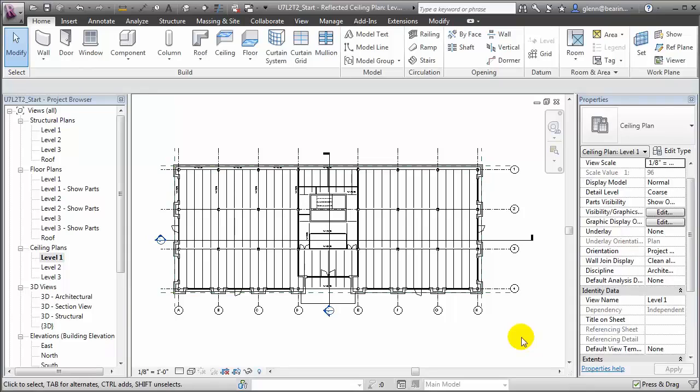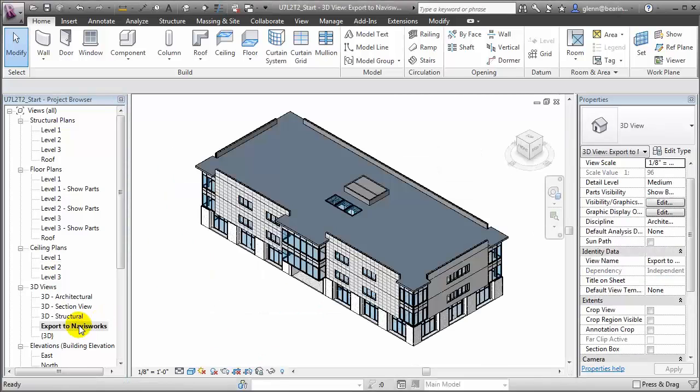Using these same steps, we can select all of the building elements that we'd like to assign to location-specific tasks from the building model on each of the different floor levels and assign them to appropriate task IDs for Zone A, Zone B, or Zone C. With our 4D task ID parameters updated, we can now return to Navisworks to link our updated building model to the new task timeline. Let's return to the Export to Navisworks view so we get all of the building elements.